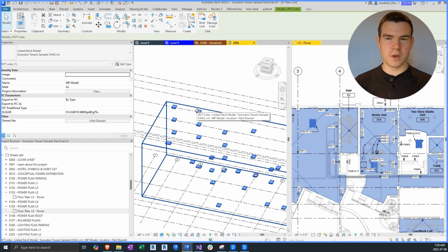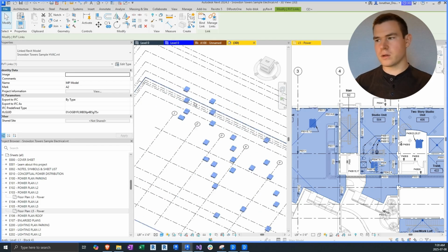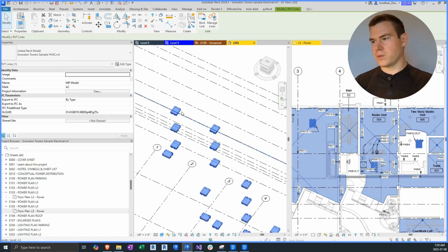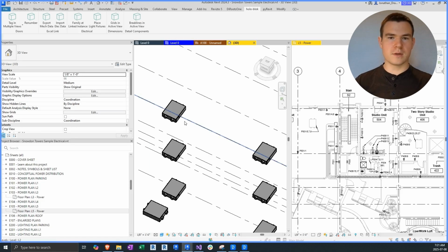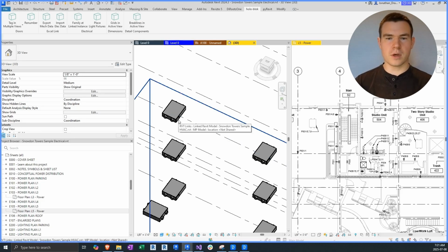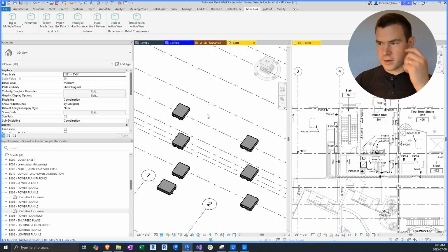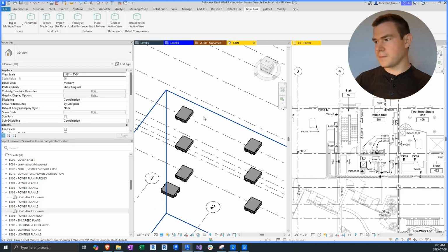Moving on to the next thing, let's say that we're in an electrical model, which in this case we are, in an Autodesk sample project, and we're looking at a mechanical link where only the mechanical units are visible. And we want to place a family instance at a consistent location relative to each of these HVAC units and maintain a link so that if anything changes in the mechanical model, our families can move right along with them while also inheriting some data from those units. So we're asking to do a few things here, but we built something that is going to do just that.